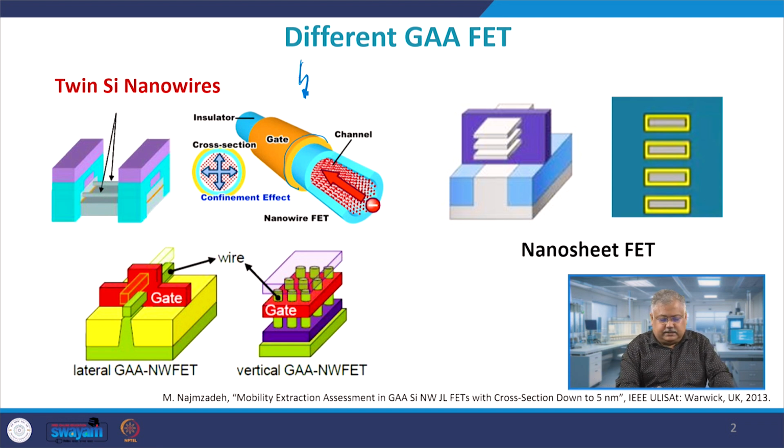One is this one which you see in front of you. Another we have already studied when we were doing FinFETs and Nanowire FETs, where this is the wire I am talking about, this side is source and this side is drain, and you have a gate here. This is not an insulated gate, but a shorted gate structure. Whatever potential you give on this gate side, the same potential goes across the whole of the channel.